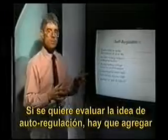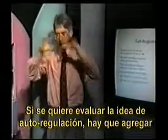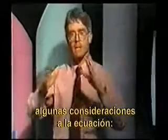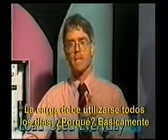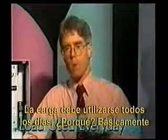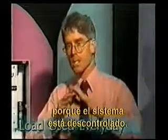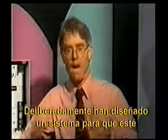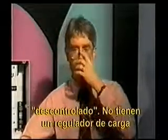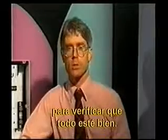Some considerations that we've got to add into the equation of even considering a self-regulating idea are these. The load has to be used every day. Why? Because basically your system is out of control. You've deliberately designed a system to be, quote, out of control, unquote. You have no charge regulator to make sure that things are right.